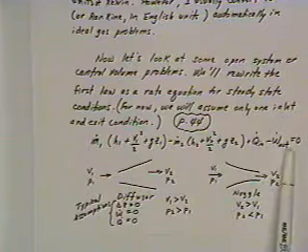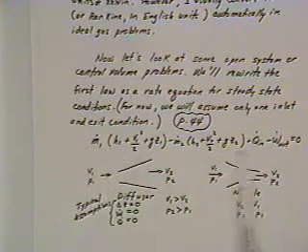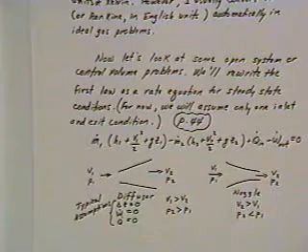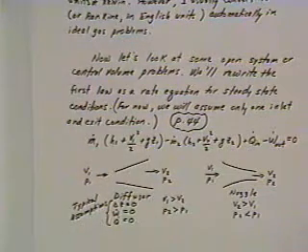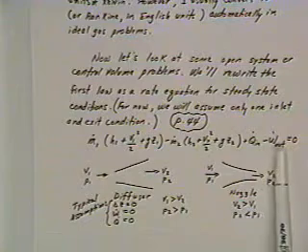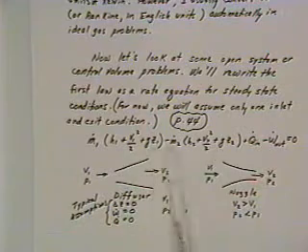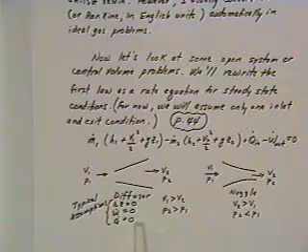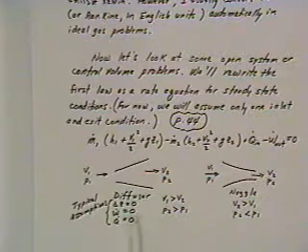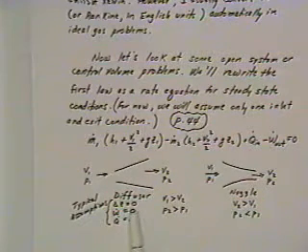And all of these things, you have to analyze each one individually and determine what terms you can throw out. If you had to solve this equation on every one, these would be more than 4-minute problems, so you really wouldn't be able to solve problems like this on this exam. In this particular case, there's no work being done for either a nozzle or a diffuser, and so that term goes out, and the potential energy terms go out. Typically, you also assume that there's no heat transfer, so the change of potential energy is 0, there's no work being done, and heat transfer is equal to 0.